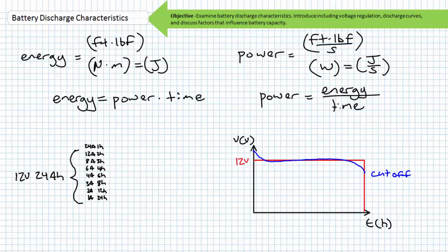Those that have trained for an athletic event are no doubt aware that a weekly regimen of hour-long training sessions have nowhere near the intensity of a 5-minute fight. It would be expected that a 24 amp hour battery being asked to supply 24 amps at a dead sprint wouldn't last the full hour. Additionally, as the battery reaches the limits of its capacity, the electrochemical reaction central to the process could be expected to slow down as active material and functional surface area is consumed.